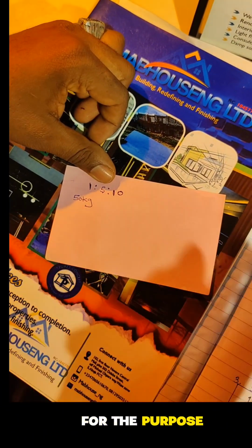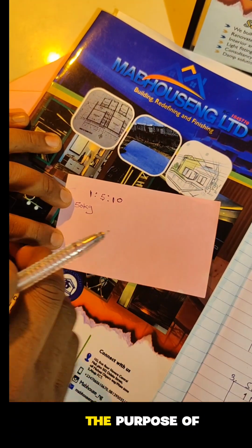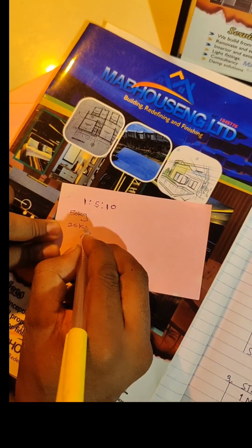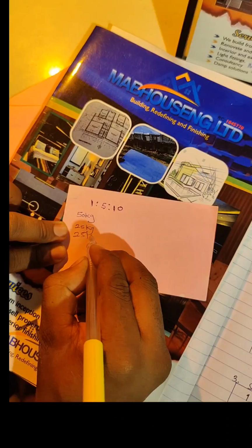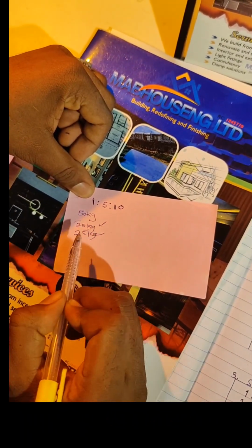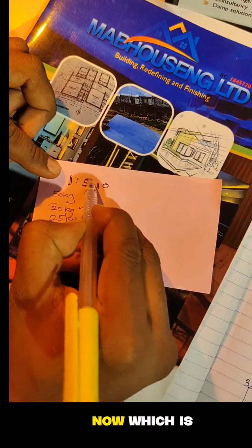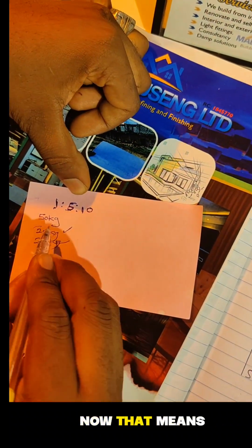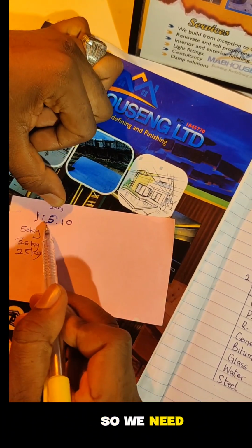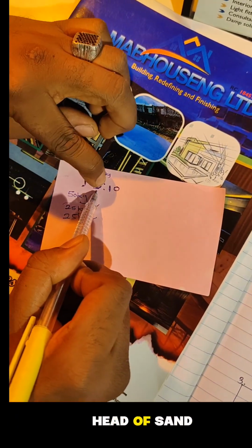So for the purpose of construction sites, mostly we use bucket or head pan. Let's use head pan for this class. So each head pan is 25 kg. That means for you to achieve this, you are going to use 2 head pans of cement to achieve this 1 ratio. For this 5, which is the fine aggregate, we have 25 kg here. So we need 10 head pans of this to make our ratio 5. 10 head pans of sand.